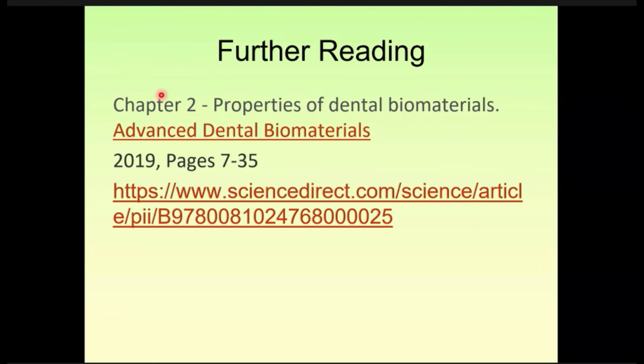The Rockwell can be used for thin sheets and for elastic materials also. With Rockwell, we start measuring with a meter. We don't need to measure the area of indentation. The system comes with a small meter, and once we apply force on the material surface, the meter will tell us how hard the material is, without calculation of the surface area of the indent. However, we need to apply force 2 times.